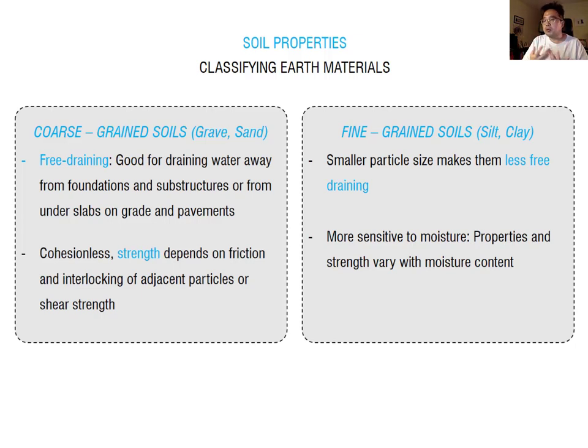We always consider getting rid of the water as much as possible, but silt and clay usually contain moisture, so it affects the foundation design. That's why we consider coarse grained soil rather than fine grained soil for foundation design. So I recommend using coarse soil around the foundation.